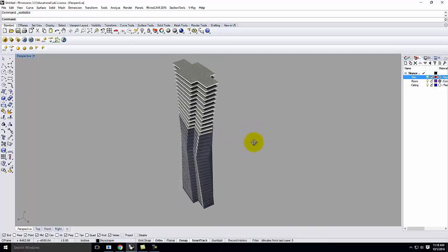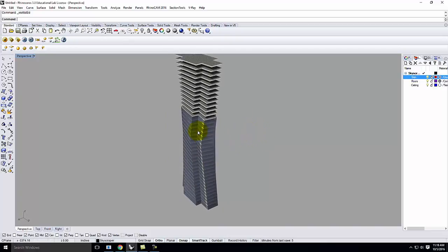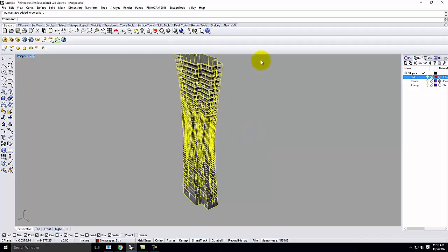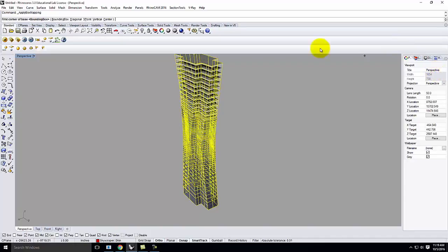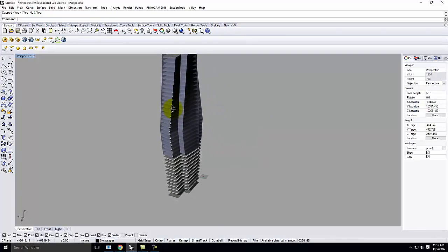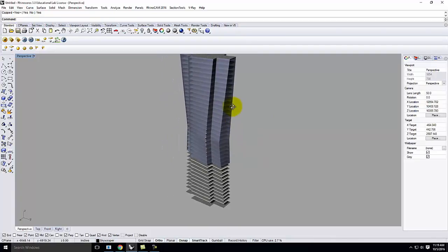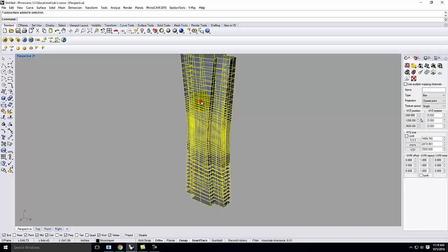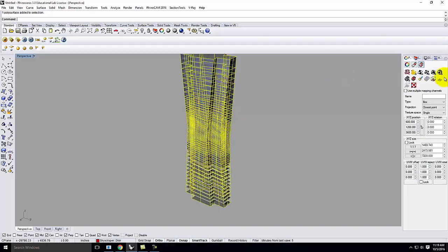Okay, and that's because the texture mapping hasn't really been addressed just yet. And so we have this skin. If I go to properties and I go to texture mapping, I'm going to start with a box mapping for it. So we'll go ahead and apply a box mapping. We'll do a bounding box. We'll do a world. We'll do it capped. Okay, and so now it's been applied. It doesn't really look much better. Okay, and that's okay. We're going to work through it. So what I'll do is I'll select the surface again, and I'm going to show the mapping widget like I did before, if you remember back to that texture mapping thing.